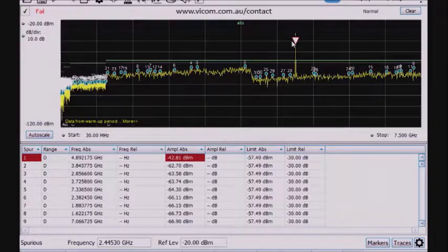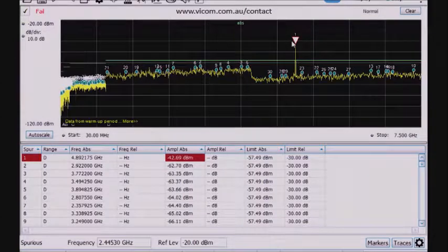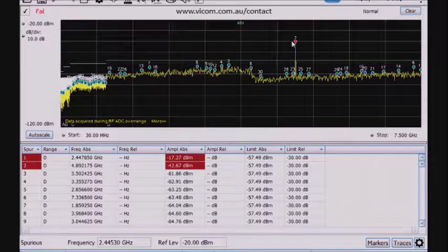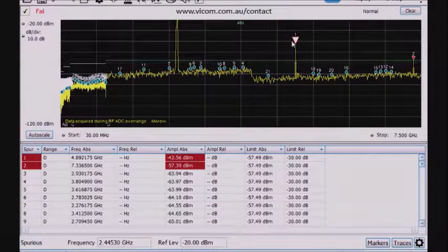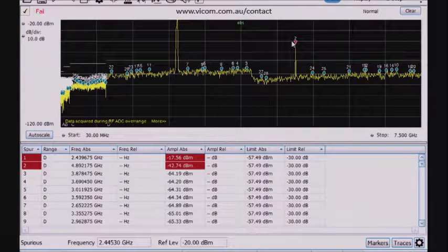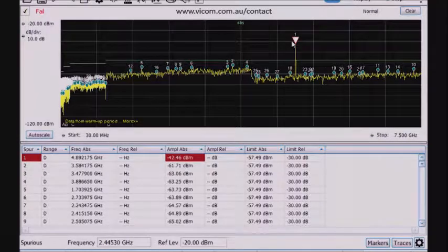In general, a CISPR peak-based search is a much faster and more conservative test to make sure I have good confidence to go past final EMI compliance, so I don't waste time in the compliance lab. I can figure this out on my own bench, provided I have enough shielding and no other signals present that might cause me to fail the test. Hopefully that gives you a better understanding of how to use a spectrum analyzer to perform EMI pre-compliance checks to give you better insurance for passing final compliance.